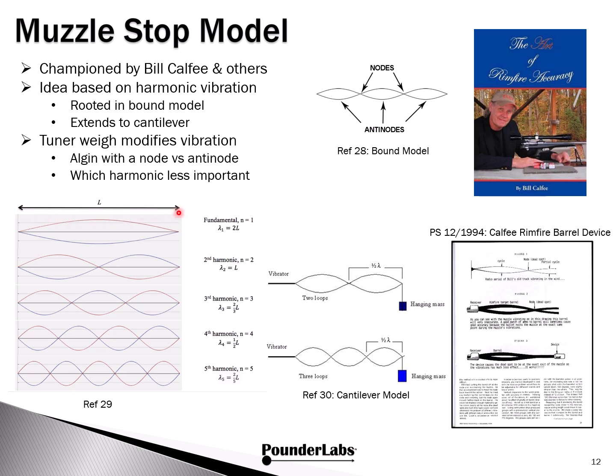Let's just say this is the length of our barrel. If we looked at the fundamental, you'll see this is a half wavelength, but at this point here, the muzzle's not moving. So as we go to the second, third, fourth, and fifth harmonic, it doesn't matter which one you're dealing with, the point is the barrel is stopped. It's not really stopped, that's just what it looks like. Whether high or low velocity exits at this point, it would not be any different.